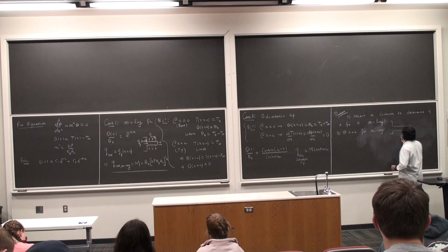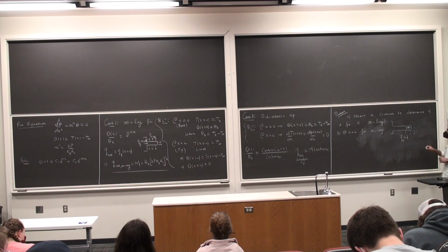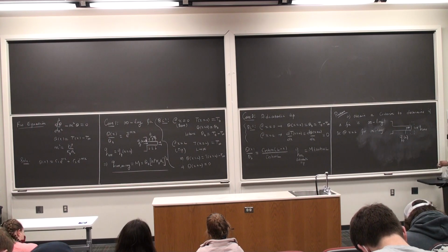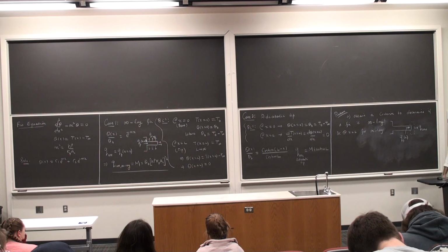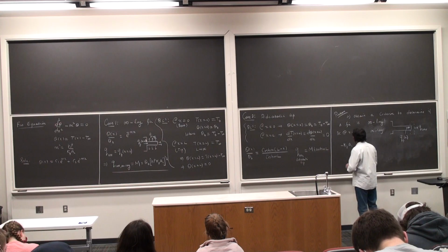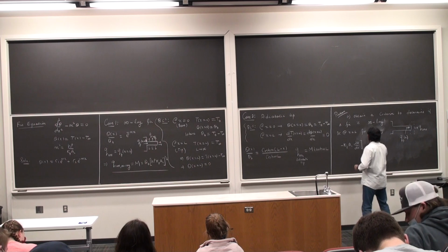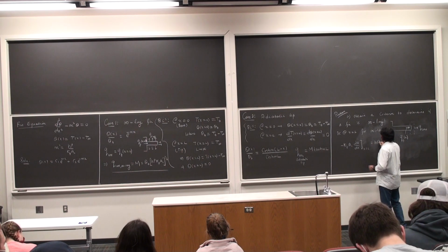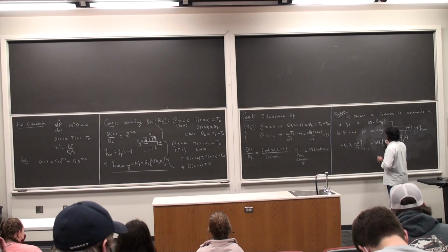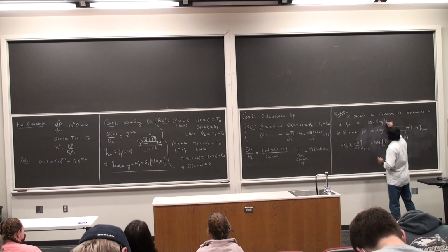This is Q fin at x is equal to L, and then this is just Q convective, okay, which is going out, and if I equate the two, minus K, area of cross section, d theta by dx at x is equal to L is h times area of cross section, theta at L, or T at x is equal to L minus T infinity.